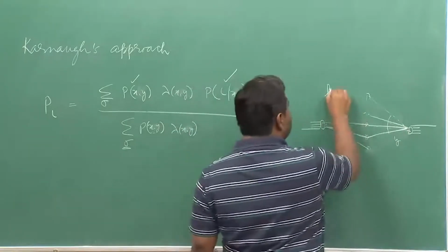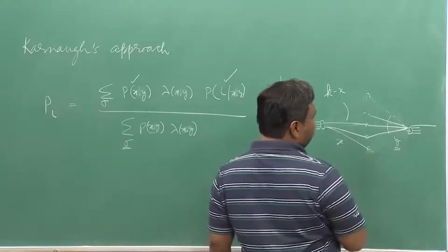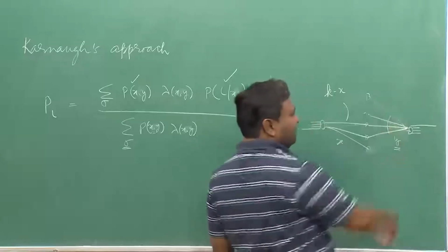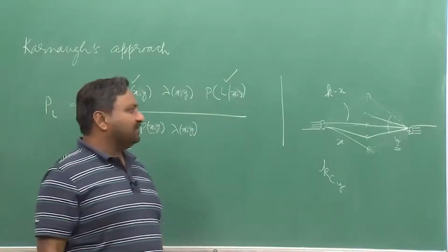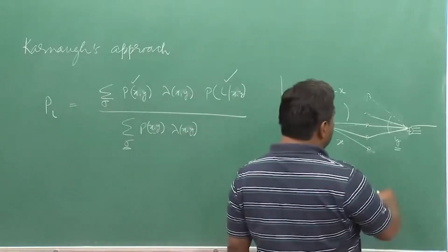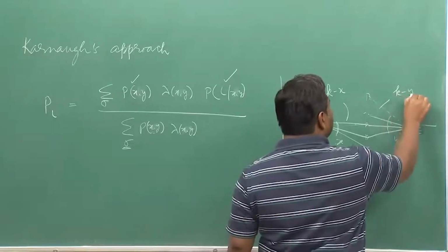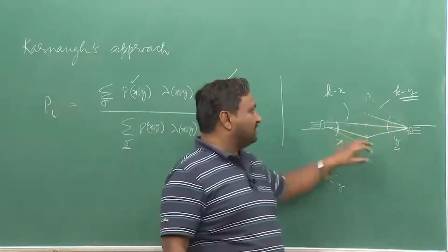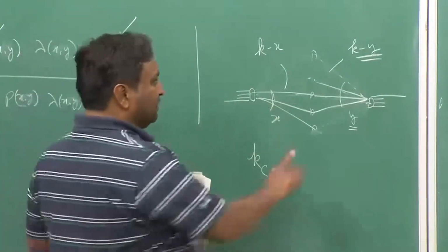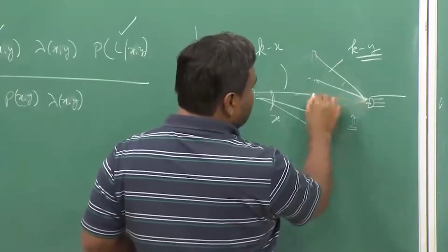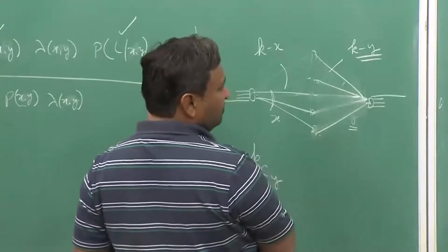Now, the remaining balance will be k minus x, and out of this y, in how many ways this y can be arranged among these k middle stage switches. This will be k combinatorial y, that is the total number of possible ways you can arrange. And of course, now you have x occupied ones and k minus y unoccupied ones. So, k minus y unoccupied ones, in how many ways they can be arranged across these occupied A links, that is the time when the blocking will happen. Okay. So, for example, when you have this possibility, these are blocked, there is another possibility this way, this is blocked, if you do this it is also blocked.